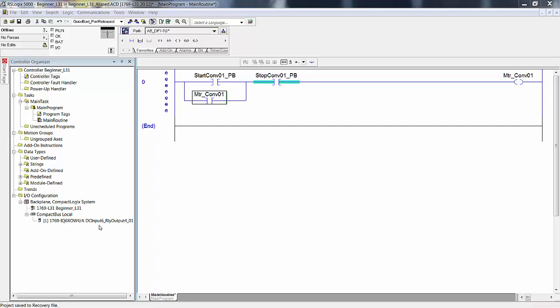This also reduces something called data scattering, which is the result of placing the I/O of a single process section in more than one contiguous location. Meaning when you first started with your, actually if you were aliasing these push buttons right now to actual I/O input points that are going to be wired to actual field input devices, push buttons, and you went through the whole process, let's say you had 15 conveyors. And so you wanted to keep everything for conveyor 1 in one location, contiguous tags, etc.